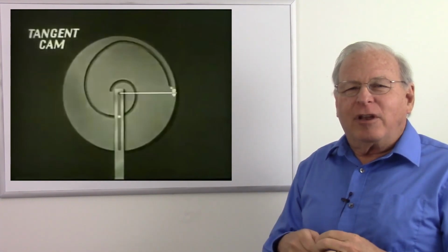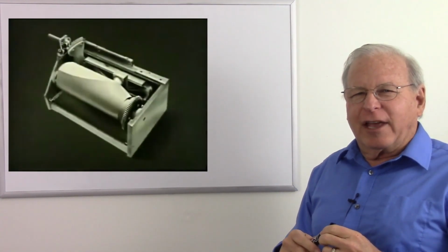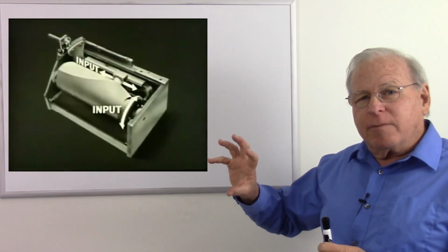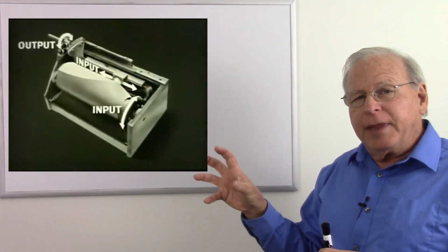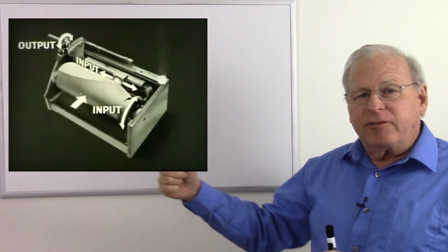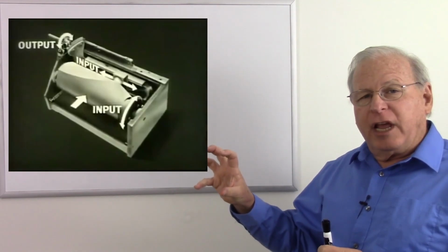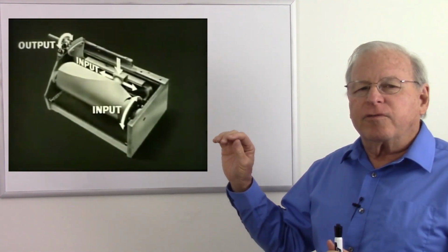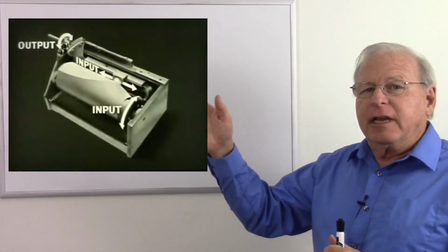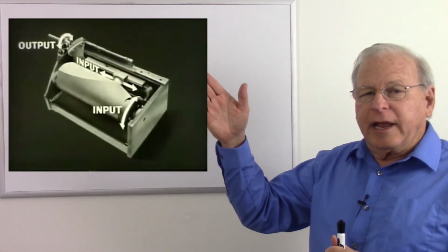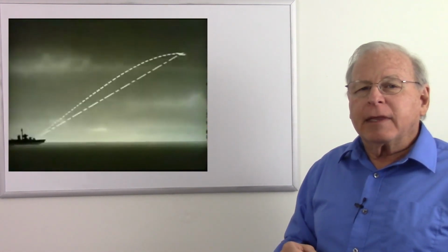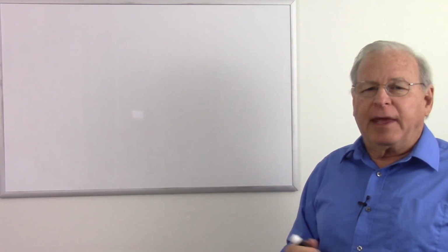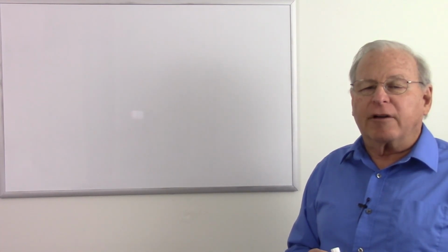And the most interesting one would be the barrel cam, which sort of looks like a shortened and distorted baseball bat. And this was a three-dimensional cam where this could be rotated to one position, and then the follower could be in different places. So depending on the angle of rotation and where the follower was, you would get a different solution. I believe these were used for firing at aircraft to get the different lead angles for the aircraft at different altitudes and speeds. And so this was the epitome of analog computers. And these kinds of analog computers have gone back thousands of years.